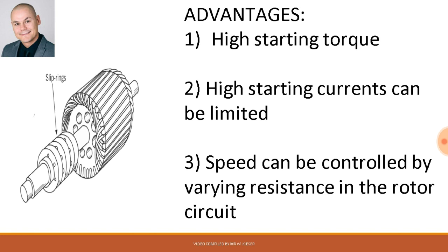The advantages of a wound type rotor: it has high start torque. The high start currents can be limited using the external resistance, and speed can be controlled by varying the resistance in the external circuit.